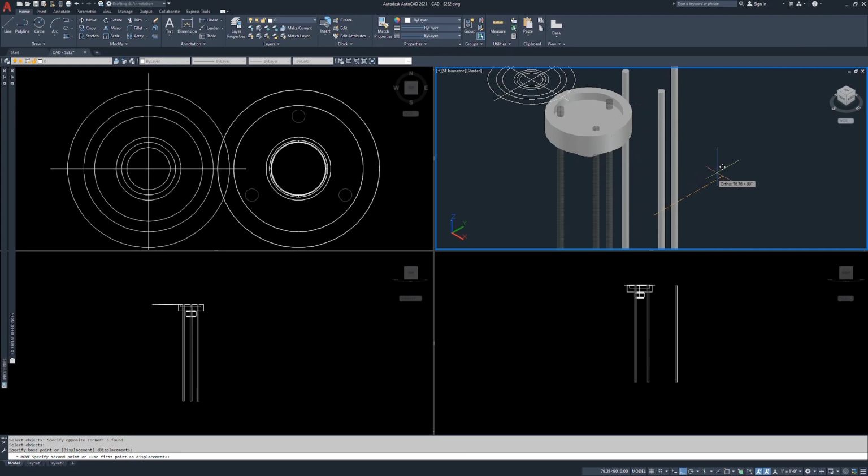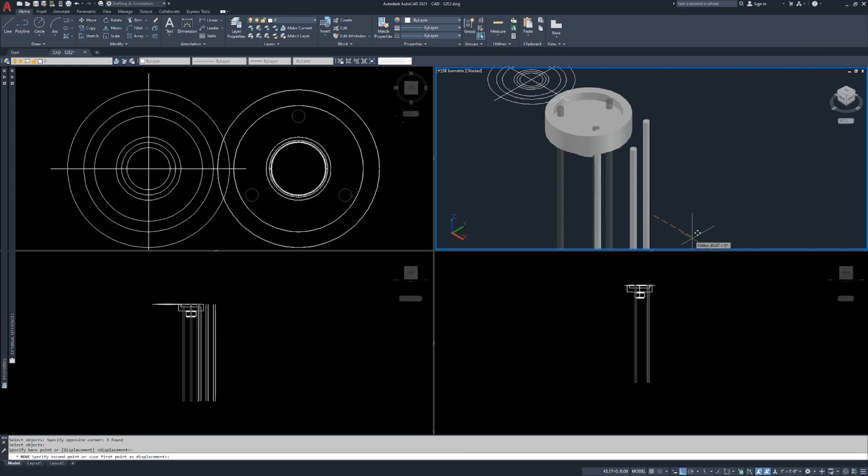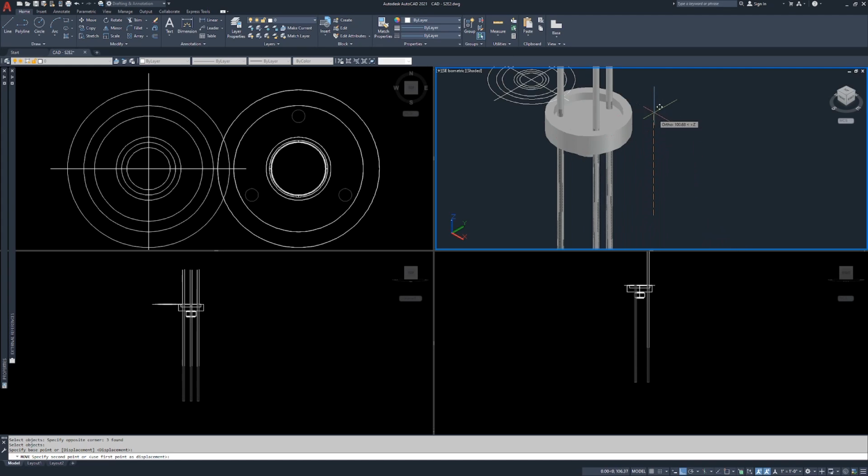in isometric, you can pull along the y-axis, you can pull along the x-axis, and you can pull along the z-axis. So if you look at the 2 bottom viewports, we're actually pulling this in Z. And the reason that works is because in the isometric view, you can actually control Z without having to use the coordinates.